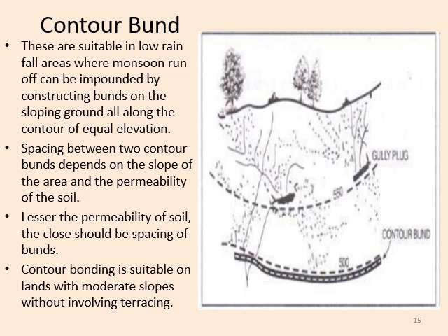If the permeability of the soil is less, the spacing of the bunds should be closer, because the runoff will be high and we have to collect a huge amount of rainfall water.